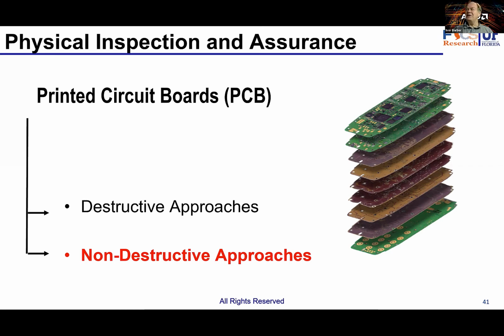What is the application for that technique? So logic locking is a technique used. I'm sure everyone is probably familiar with logic locking, but it's a technique used to basically implement or insert your key as a trusted foundry after you get your chip through the fabrication. So you hold the key and you put it in, you run your functionality when the chip is fabricated and is back on a trusted site. And by putting in that key, you will be able to run the logic, right? So if you don't have that key, then you won't be able to run the logic.